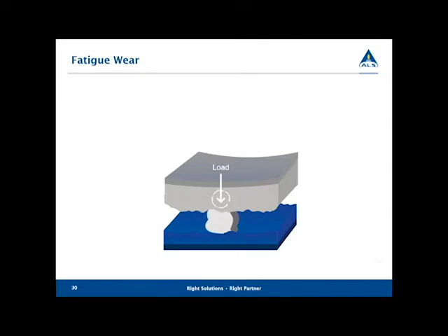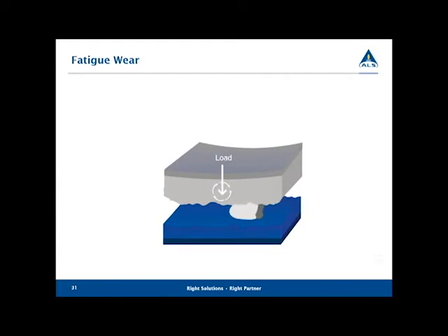And we could also have fatigue wear. Fatigue wear comes in from another hard particle, perhaps from the cold welded particle that broke off, or an external particle coming in from the outside, due to a bad breather or a bad filter, something like that. Anyway, it sets up a situation where it's larger than the tolerance between the two surfaces of the componentry. And by doing so, it sets up a bridge between the two, and that load can actually start to compromise that surface.